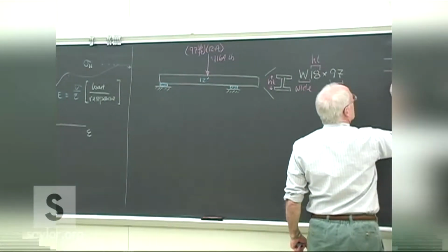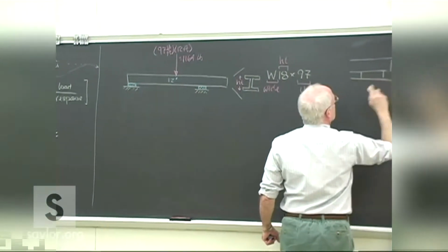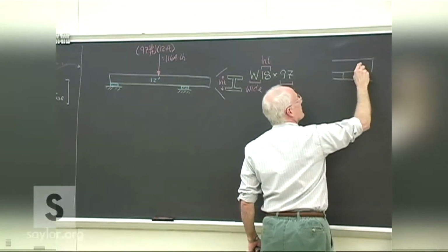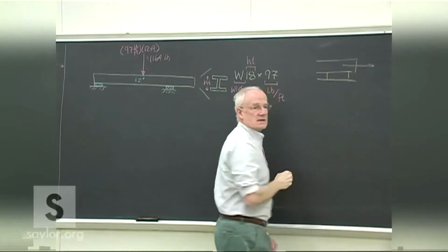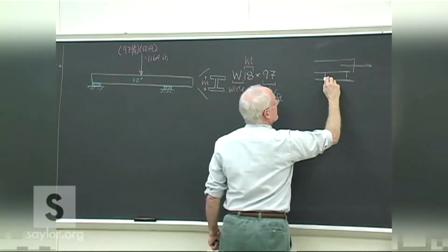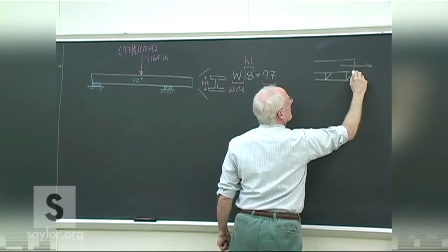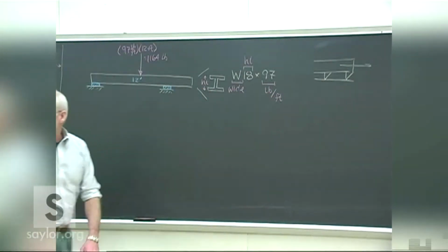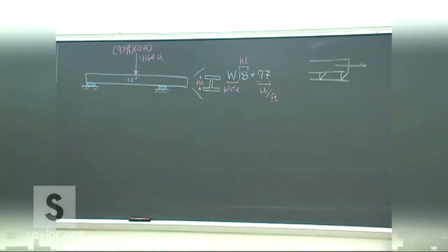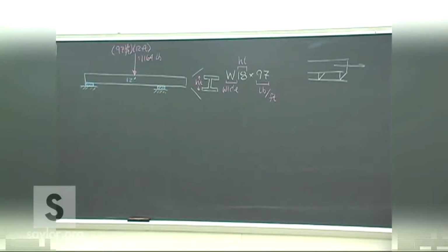We've got the beam there and the shear pad there. If the beam grows in length because of thermal effects, then the shear pad can absorb that by shearing over a little bit, and then when the thermal changes disappear, the pad can return back to normal, and the beam's nominally as designed.